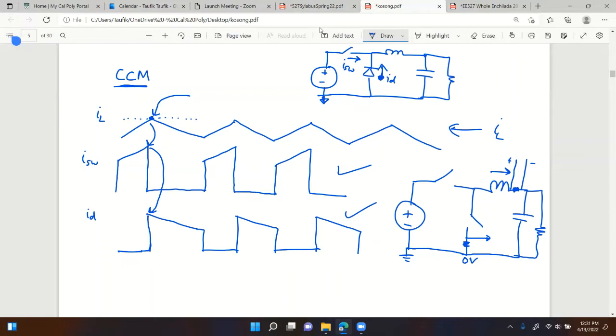The switch is more on the input side than the inductor. Good point. It's closer to the input, but both of them contain the same information. As soon as the input voltage changes, the inductor current slope will also change. So even though it's connected to the inductor, it would actually be as fast as sensing it here.